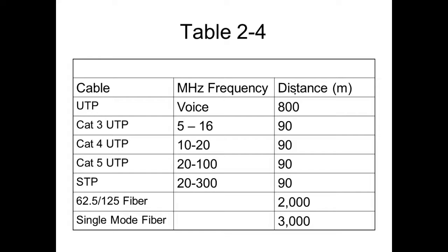Because if I try to send a signal through a cable, there's got to be current involved. We try to make the current as small as we possibly can on a network, but there's still got to be an I involved. And if I send an I through an R, what happens? We get a voltage drop, and we call it a line loss. So the 100 meters is not the impedance. It's the resistance of the wire.